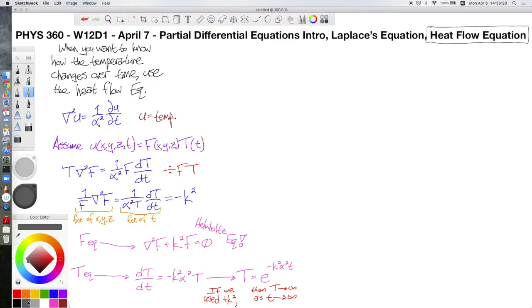And to proceed any further, we need a specific problem. So let's bust out a specific problem. Let's take an infinite plate with a width of L, and we're going to hold one side at 0 and the other side at 100. And then that 100-degree side, we are going to switch to holding at 0 degrees, starting at t equals 0.